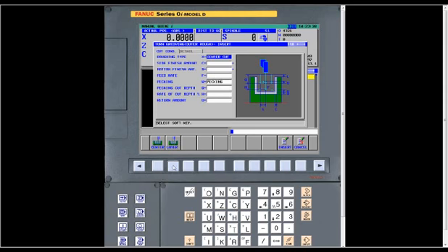If you want to use layering, it only takes layers out. It'll go down so far, rough it completely out, go down a little further, and rough it completely out. That's how that works. But if you use center cutting, then you can leave a certain amount of finished stock. You can see both of these next two fields have asterisks where you don't have to answer that information.